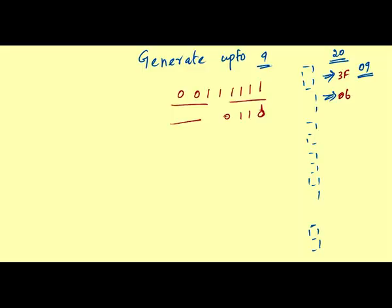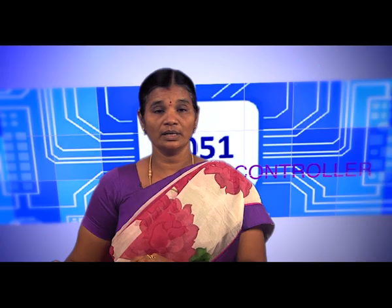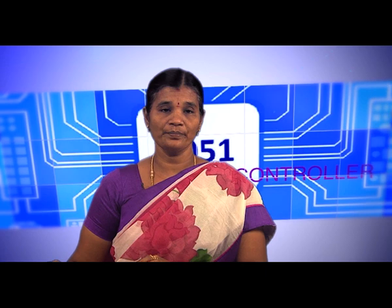So, this is for 0: you have to give the value 3FH. For 1, only C and D are 1, right, the remaining are 0. So, that fully gives 06, you have to give it. Likewise you develop and give it. Okay, so I think you can easily generate the same program.